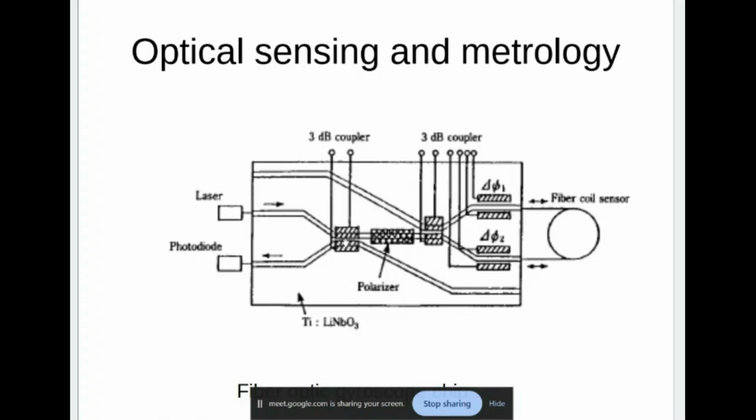So in order to do that, you have to have all this circuitry. Like you must work on single mode waveguides. You must have a polarizer, a 3 dB coupler is there here, and a phase shifter is there here. All these things are needed. This we can put on a small chip. In the earlier days, people used to use discrete components and then put them in between the coil. Suppose you wind the coil around a tiffin box size coil. In between, they used to put all these things. Now that is also reduced, and you can put all this in an integrated optic chip.